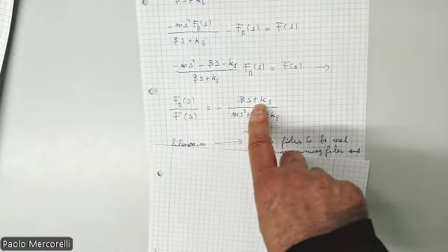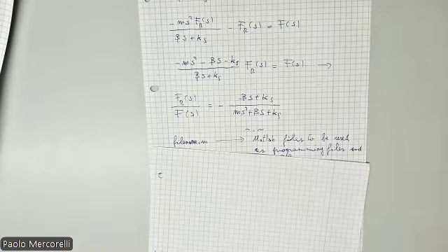What is the numerator? The numerator reflects, as before, the transformation we are considering. You remember, in the position we had the coefficient 1; in the velocity, s, because velocity is the derivative of the position. When we consider the acceleration, the transfer function between force and acceleration, we have s squared. Why? Because s squared reflects the second derivative of the position.